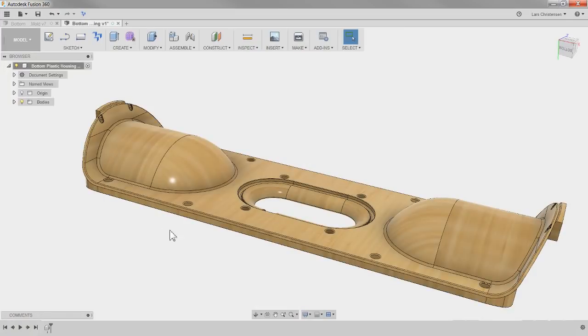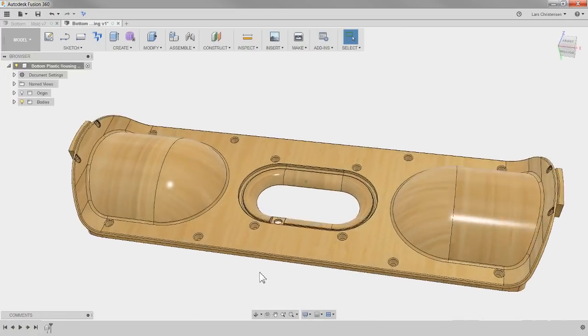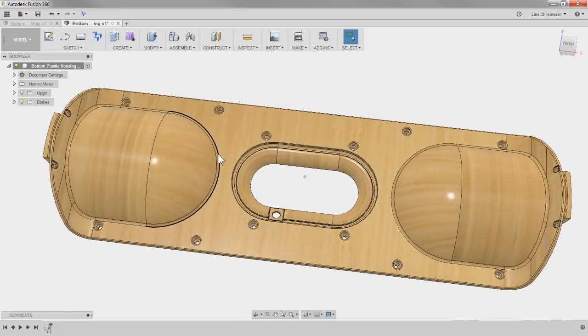Now there are a couple of things we need to do before we can divide this up. The first thing is we've got to plug any holes inside the part where there would normally be core pins or something inside the part. So through holes, for example. There's a through hole in the center of this part, so we will block those off. And the second thing we will do is create what is called a parting surface. You will see that in a second as we get to it. So first things first, let's talk about plugging up any holes in here.